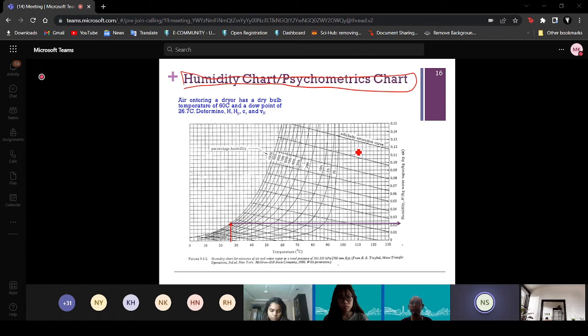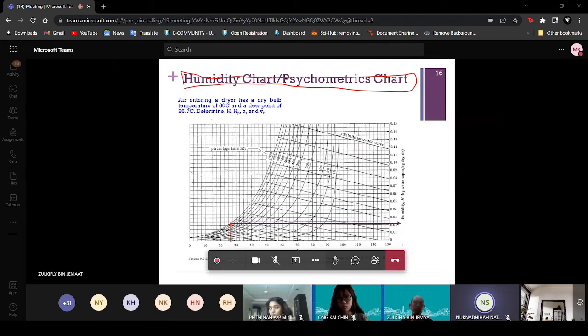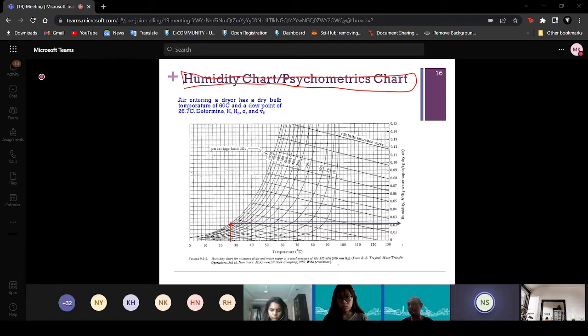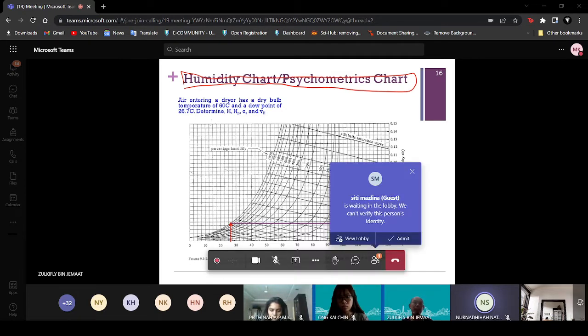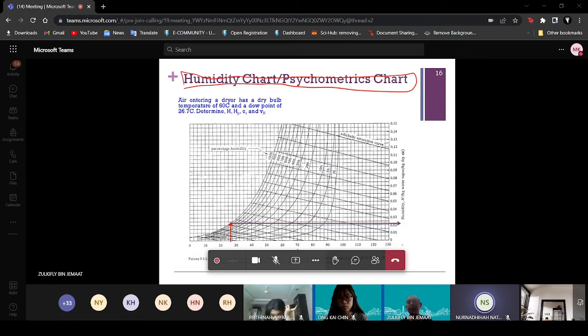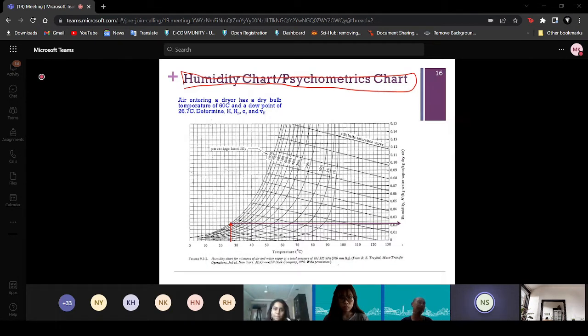Whereby you have to find the RC, and then later on you can find the time. Where you consider only convection, and later on I will expand the equation to include radiation and also conduction, and then we'll be finished. That is for today. And then next week, Dr. Sharida will continue on a little bit on the application. For example, you have a full range of tray dryer, or you have packed bed dryer. So what is the equation that you can use to calculate straight away the time for drying, for example, and the rate of drying. So she will discuss that.